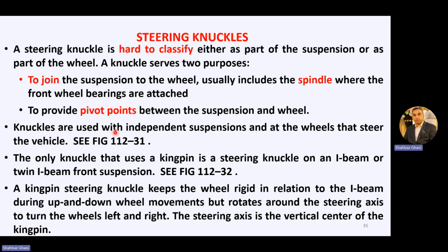Knuckles are used with independent suspension and at the wheels that steer the vehicle. The only knuckle that uses a kingpin is a steering knuckle on an I-beam or twin I-beam front suspension.